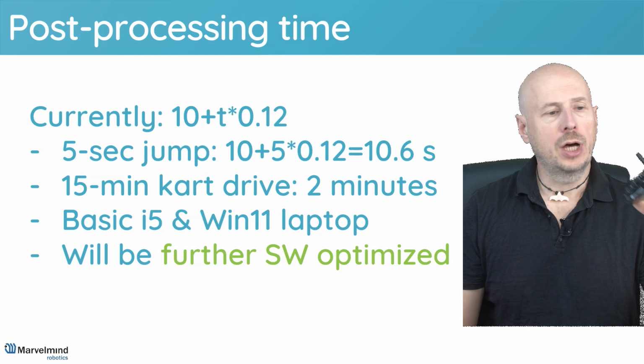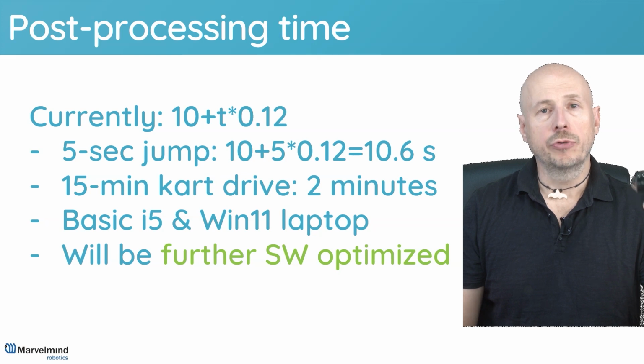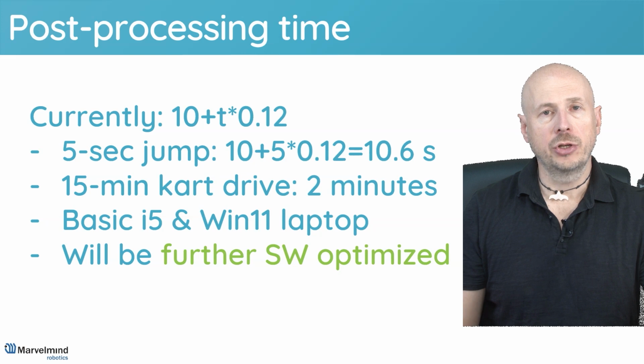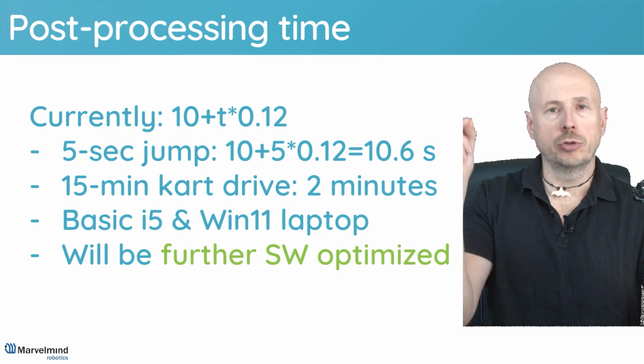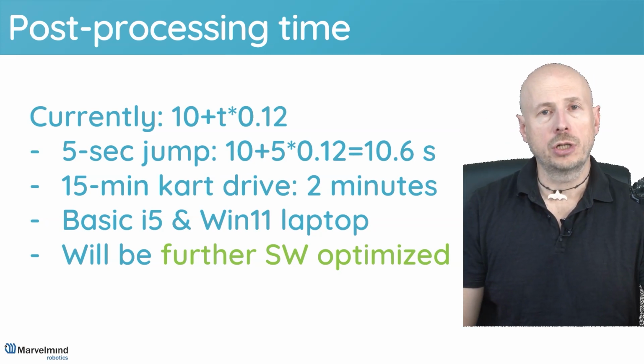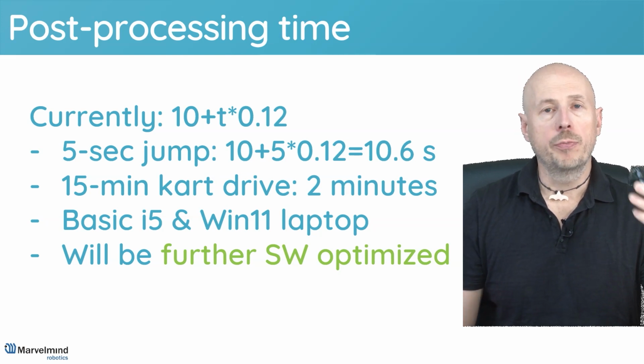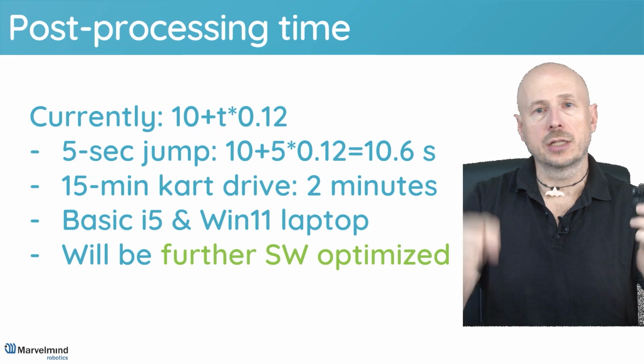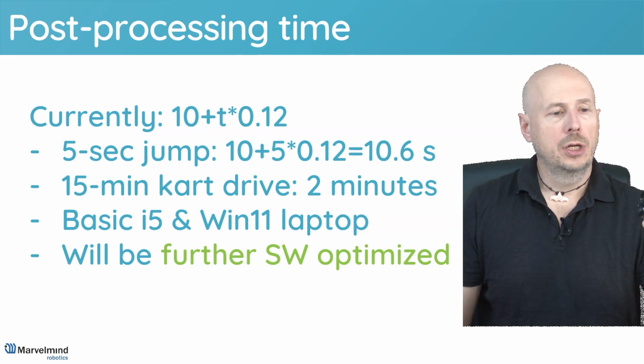But at the same time, IMU from their mobile beacon has plenty of data, which is coming very quick, 100 Hertz update rate, and it's impossible to send it with typical radio channels because there will be not enough bandwidth, particularly when I have many mobile objects, for example, many cards moving on your track.